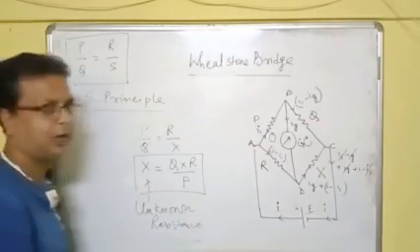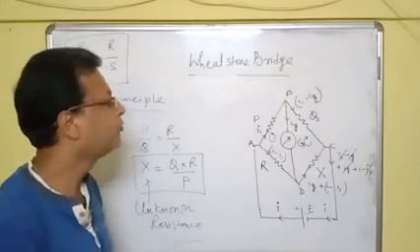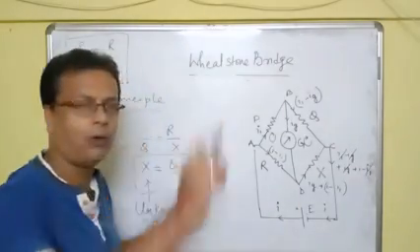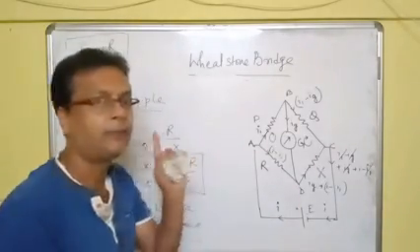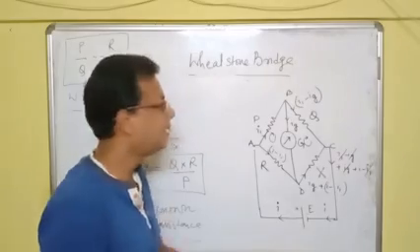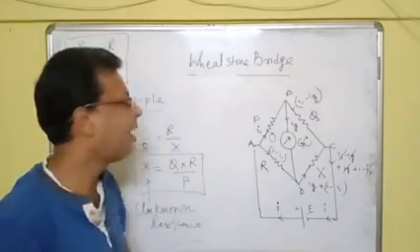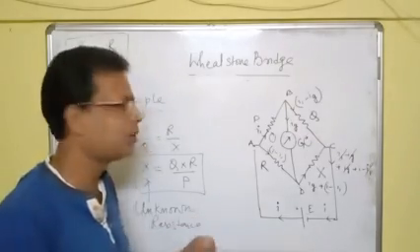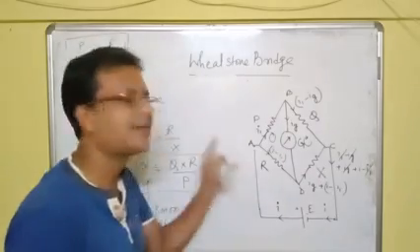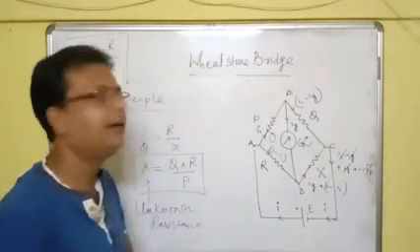So if you know Q, R and P, this unknown resistance can be found out. This method is used to find out the unknown resistance of long wires by means of an instrument called a post office box. A small unknown resistance can be found by another bridge, a modified Wheatstone bridge known as the meter bridge. That I will be explaining to you in the next class.